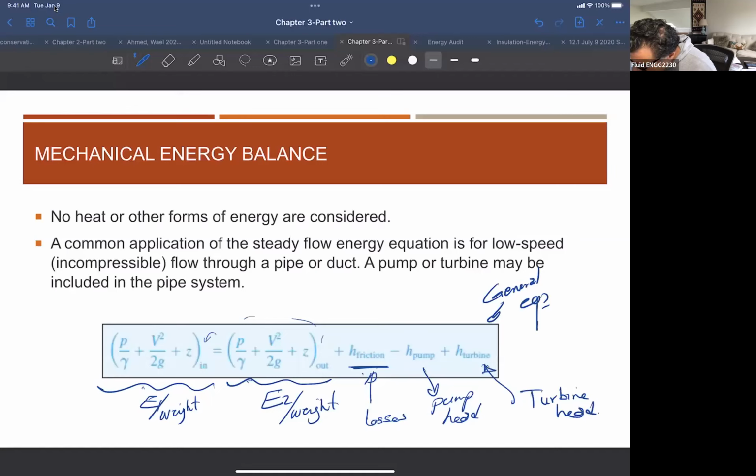You see here now from the Bernoulli equation, ideal flow. Now I added this term here, I kind of converted it into the real case, but in a simple form. Of course, I'm not going to look into what the frictional losses will be. In chapter 6, or 7, I think 7, we'll go back and study how we can determine these losses, how much these losses are.